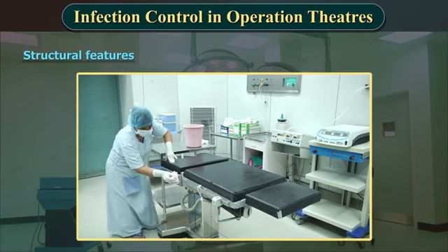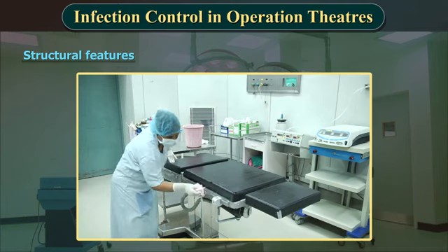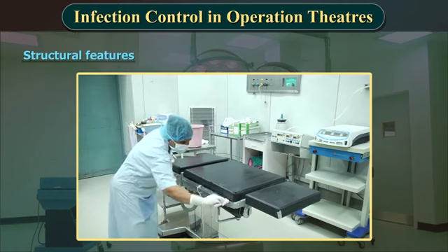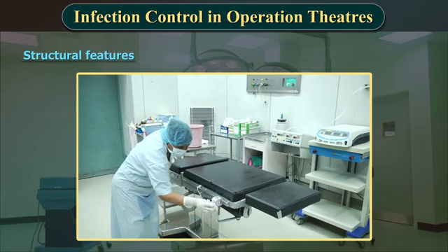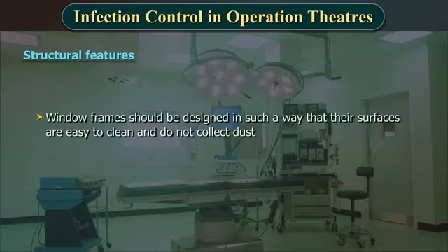The surfaces of floors should be impervious to moisture, easily cleaned, stain resistant, comfortable for long periods of standing, and suitable for wheeled traffic. Window frames should be designed in such a way that their surfaces are easy to clean and do not collect dust.